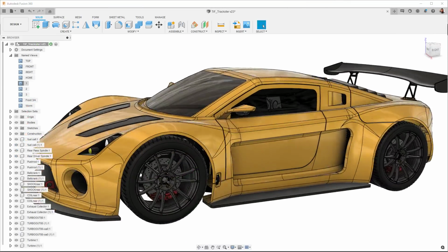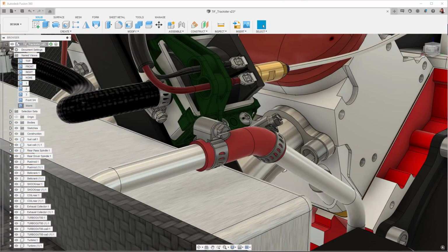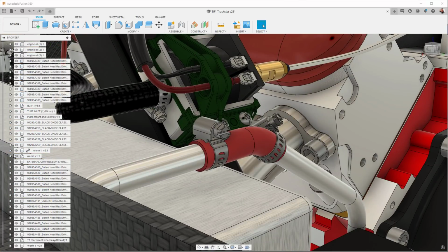If you use distributed or bottom-up designs, this next feature is a great one. You can now provide visibility overrides for linked components inside the higher level assembly. Previously, the only way to hide components of a linked design was to either edit in place or edit externally and then update references. This now makes a temporary visibility change just inside the document you're working on.